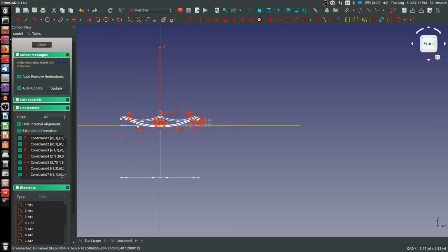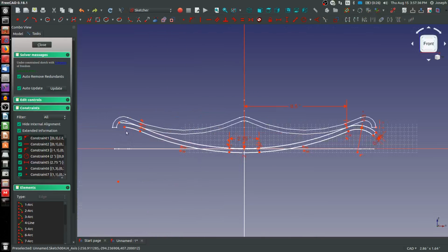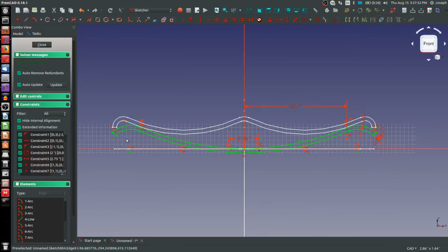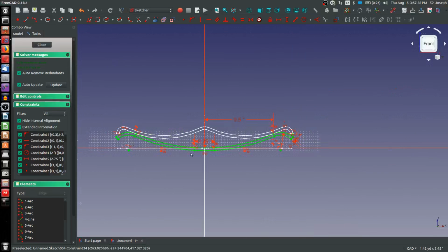Choose horizontal down here. That went horizontal the wrong way. So I'm going to make the point of revolution horizontal instead, and that should calm it down a little bit. Horizontal, equal, horizontal. And now I simply draw a line from constrained to constrained, and there's our sketch.